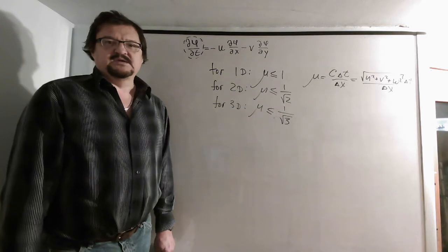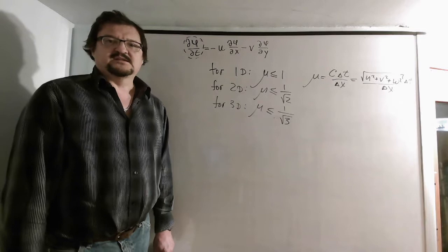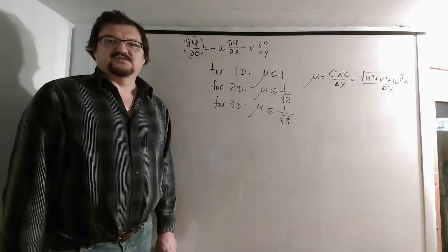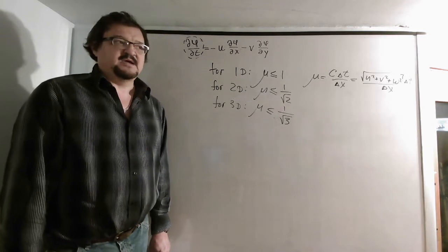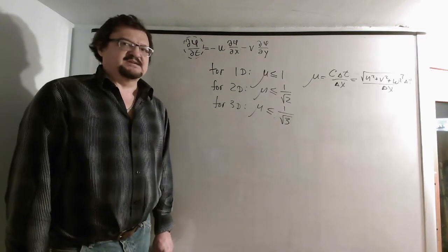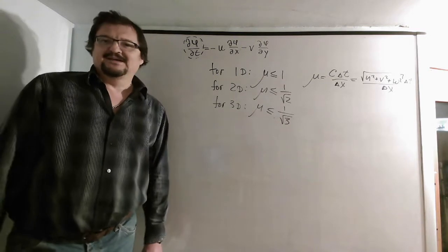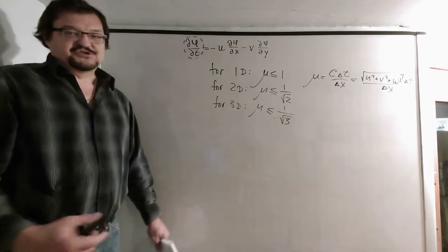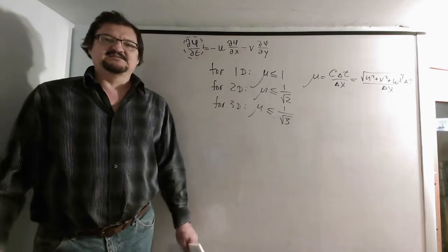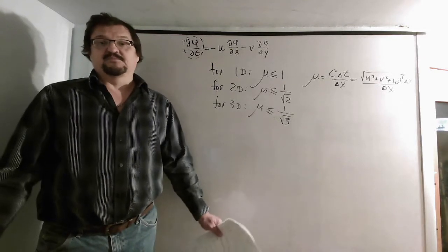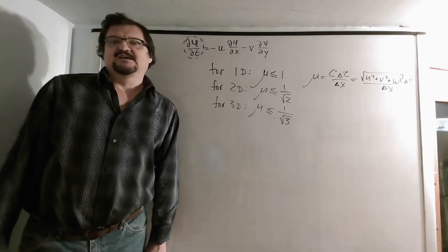One of them may be to make your stability criterion more restrictive, say by a factor of 2, so you effectively run with half the time step, and run it again and see if it blows up. Or you may discover that your solution has improved, which it should because the time step is smaller, but also because when you have constant instability, it generates excessive noise, even though it may not blow up, that can affect your solution.